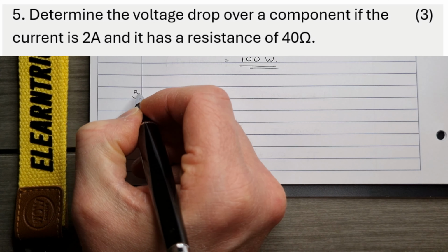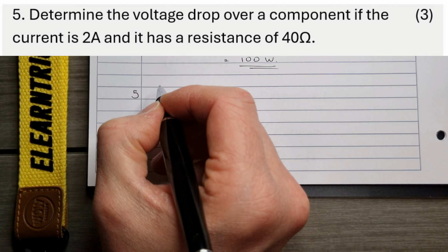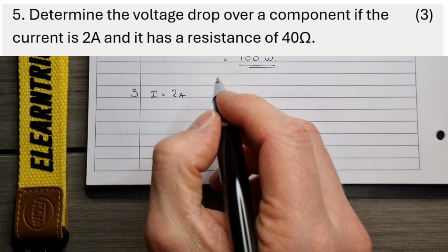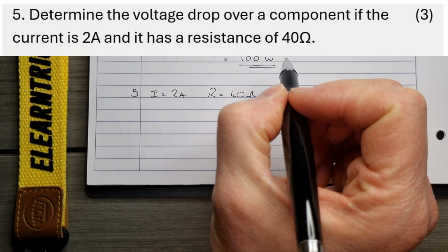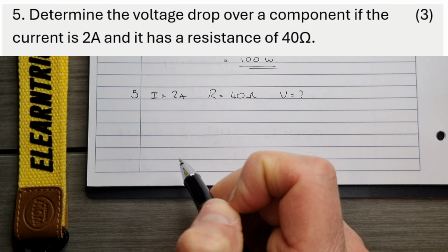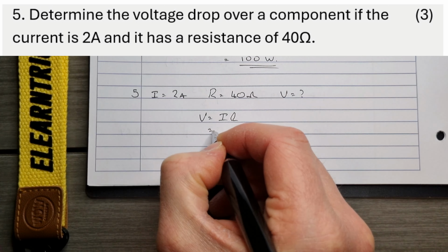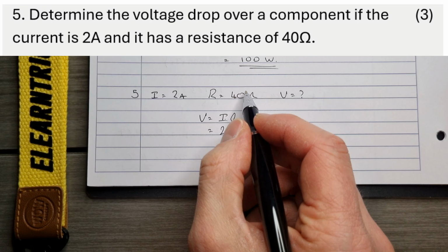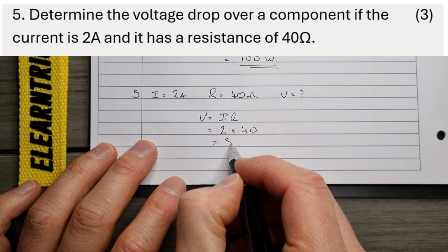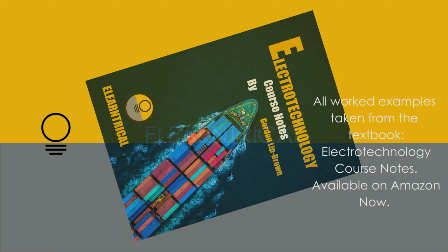Question 5. Determine the voltage drop over a component if the current is 2 amps, and it has a resistance of 40 ohms. Well, we're being asked for the voltage drop here, and we've got I and R, so this takes us to Ohm's law, which is V equals IR. In this case, our current is 2, our resistance is 40, so we've got 2 times 40, which is 80 volts.